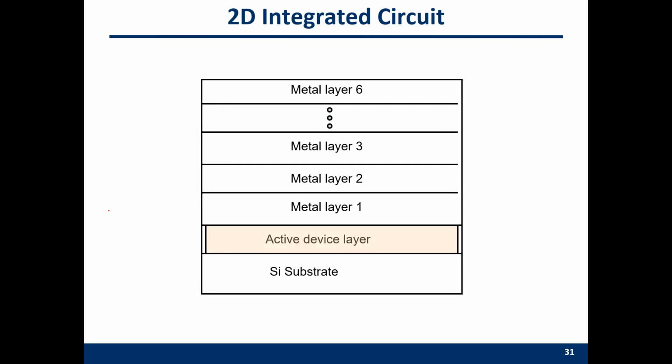And of course, FPGA also need transistors to build FPGA boards. But we can use some more advanced process technology to implement those FPGA. One example is the 3D integrated circuit. So this is the example of a traditional 2D. You have multiple metal layers for the wires to implement your interconnections. And we also have an active layer for the CLBs. This is a traditional design.